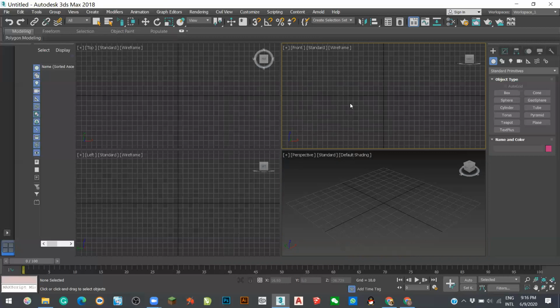Then the other one, because I don't have any object, I can demo this one. I key in one more time, so it will be good. Come back, or you press and hold, or here. This is select. This is select by name. This is select object, and this is move. The shortcut for move is W. Just press W, and you can move your object. Later I will go on with the demo. And this is rotate. The command for rotate is E.